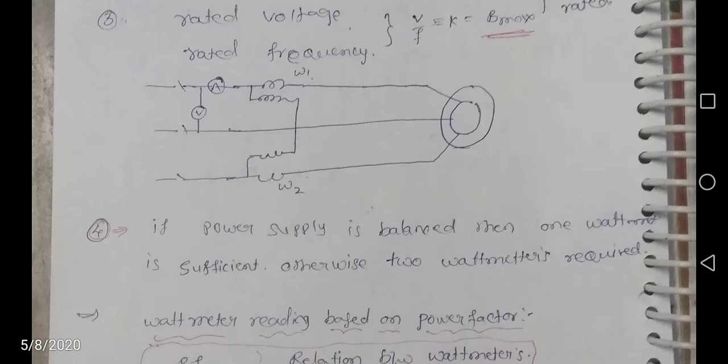If the power supply is balanced, then 1 wattmeter is sufficient. Otherwise, 2 wattmeter is required.